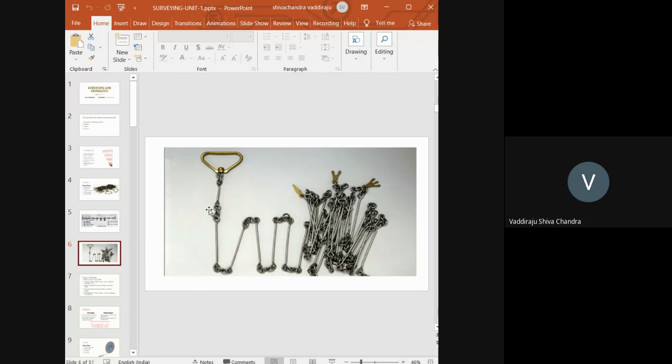You can make the link straight by beating with a hammer. Yes, sir. At home, when we are hammering a nail and it bends a little, what do we do? We hit it again with a hammer. The same we can apply here, right? If a link is bent, we can make it straight again by simply beating it with a hammer. Similarly, if a ring is worn out, if the ring opens up and comes off, you can fix it, right? Yes or no? Yes, sir.